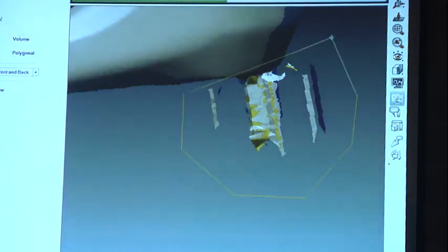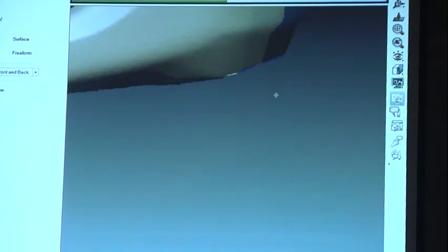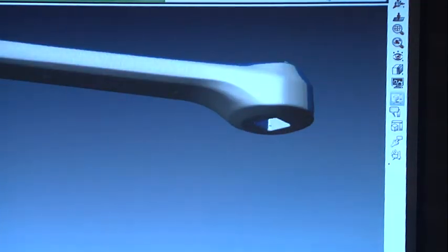And in this case, I'm removing a little bit more than just the fixture because I already covered that surface with setup number 1, so it doesn't matter if I get rid of a little bit more. I want to make sure I remove the full fixture in this case. And once I'm done, I click Continue.